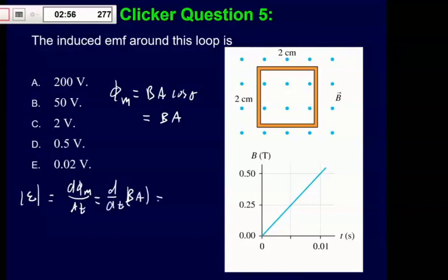So like I said, we have to now decide which one of these is changing. For us, the one that's changing is the dB/dt. To make this quantitative, we look over here on our curve to figure out just what that dB/dt is. What's nice is it's a linear setup, so basically it'll be the slope of this line here.